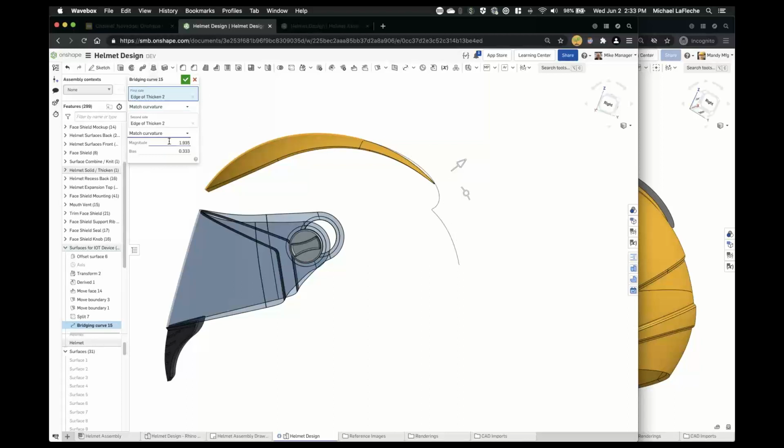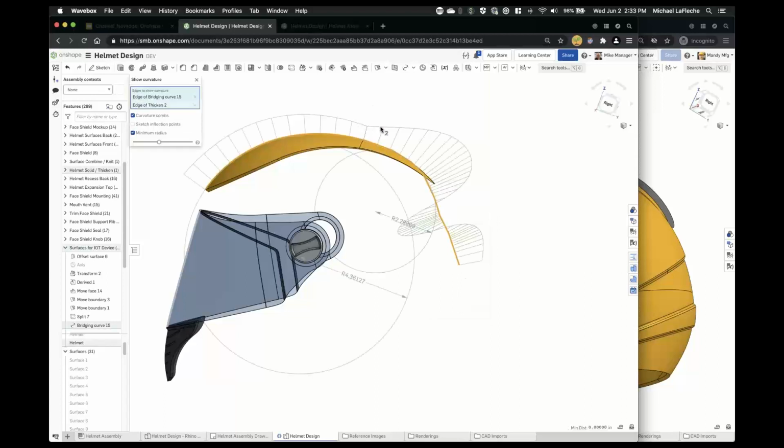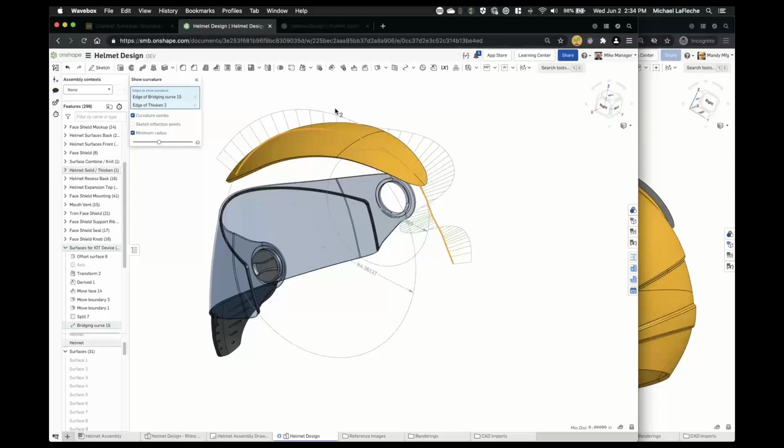and what that will do, let me just change the bias here. That's a little bit strong now. When I go to curvature control, something like that. And if I look at the curvature now, you show curvature on here and here. Now you can see that it's a nicer blend, when you're going from C1 to C2 continuity.